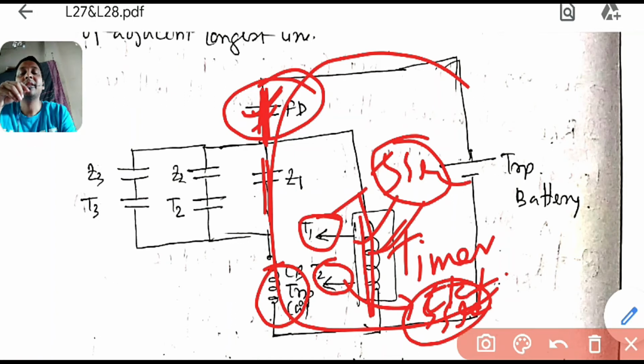So suppose it was in Z1, so it is in the first section, that is 80 to 90. Then Z1 will send, Z2 will also send, and Z3 will also close, because it can be sensed by all three relays, as the first section is common for all three.